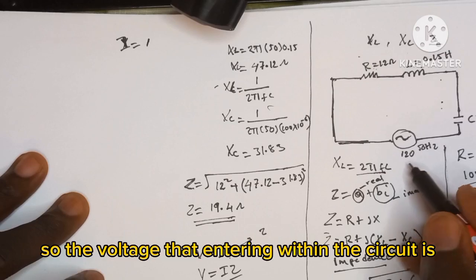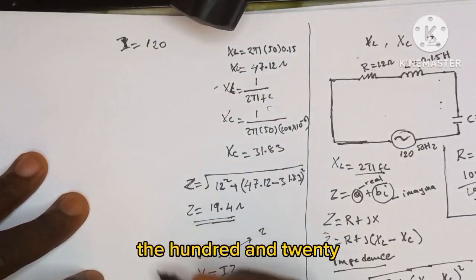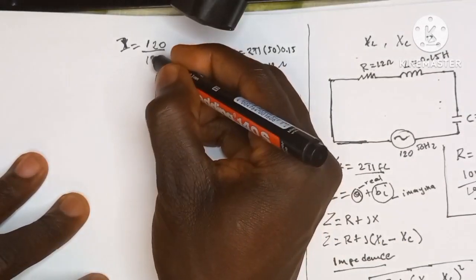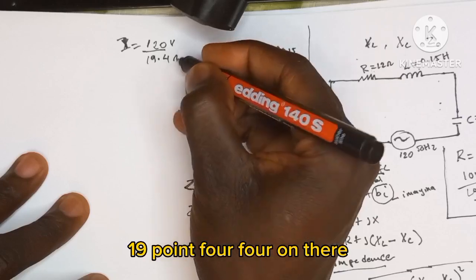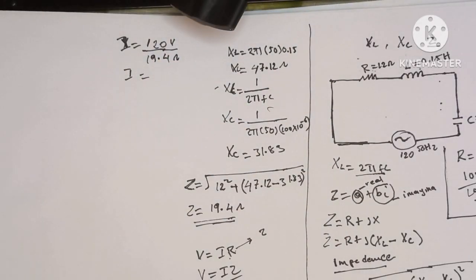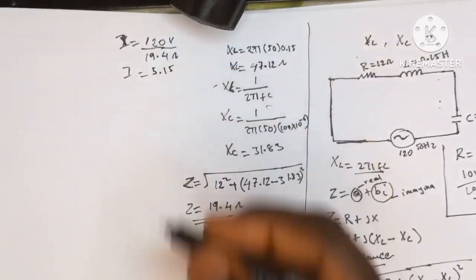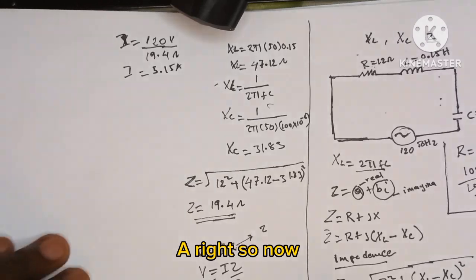So the voltage entering the circuit is 120, dividing that by the impedance value, which is 19.4 ohms here. This is going to give us 5.15 amps.